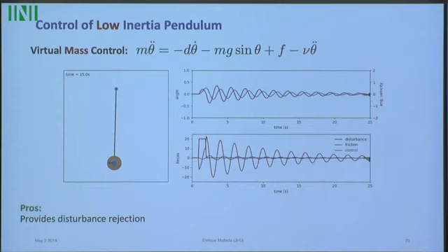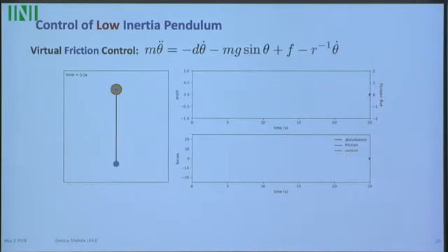It provides good disturbance protection. Arguably, this is fine, I agree. But it still is hard to regain steady state, and the control effort is pretty high. So let's see what happens if, instead of that, you increase the friction for the same low inertia system.